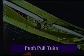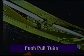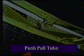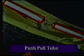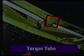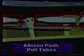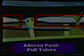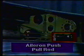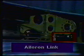Numerous push-pull tubes and rods are used in the flight control system. Some of these units are sometimes referred to as torque tubes. The best rule of thumb is that if it moves back and forth, it should be called a push-pull tube. If it rotates, it should be called a torque tube. The unit that transmits motion to the ailerons through the wing is called the aileron push-pull tube. The smaller unit that connects the aileron to the aileron bell crank is the aileron push-pull rod, sometimes called the aileron link.